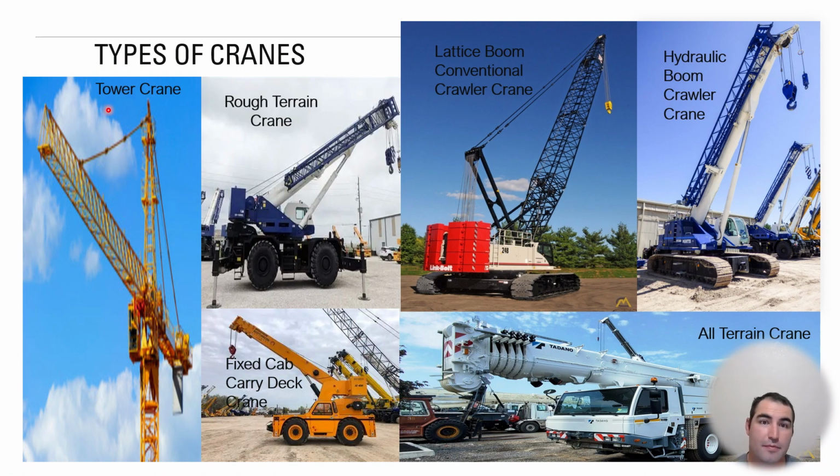So first off, here on the left, it's a tower crane. You see these on high-rise buildings and sometimes heavy construction projects, but mostly they're there to build vertically, not horizontally. This is a rough terrain crane. You do see these quite a bit on heavy construction projects because of their versatility. The one down here is a fixed cab carry deck crane. By carry deck, it means you can put a load on the deck of the crane and transport it,